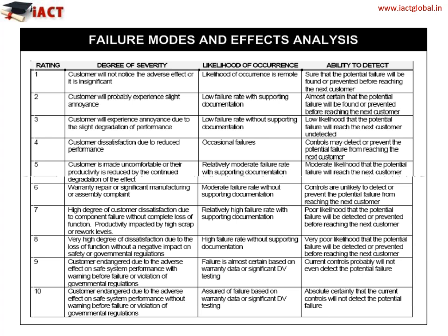Occurrence rating is an indicator on a scale of 1 to 10, which indicates the probability that the failure mode will occur. For instance, an occurrence rating of 1 indicates that likelihood is remote, whereas a rating of 9 or 10 indicates imminent or certain failure.